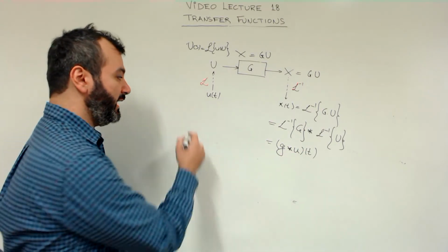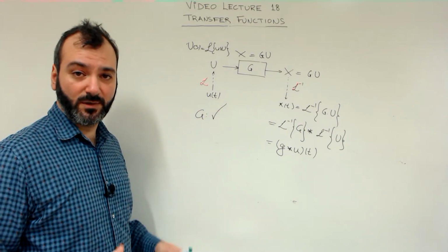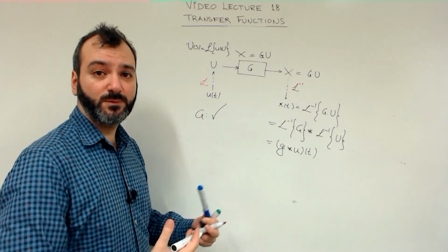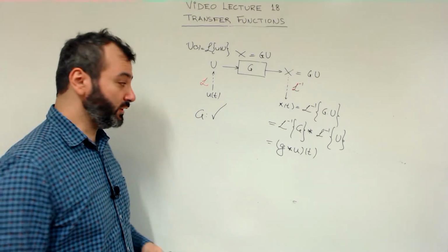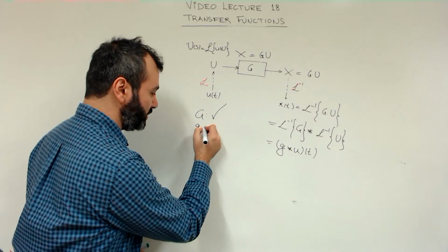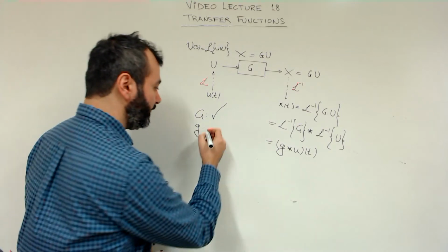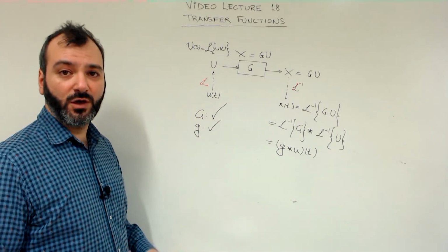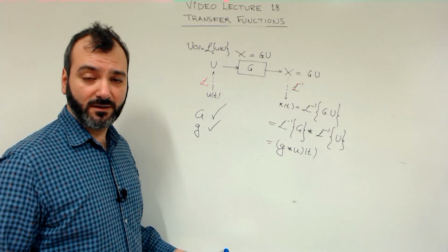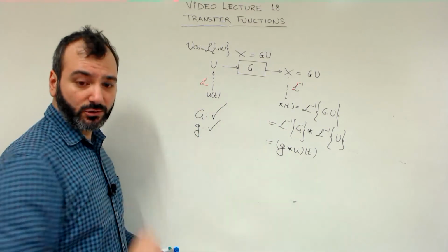In other words, if we have g, we know everything about the system. We can determine any response of the system given zero initial conditions. If we have the impulse response of the system, again we can determine the whole dynamic behavior of the system. We know everything that is to be known about that system. So this much about transfer functions.